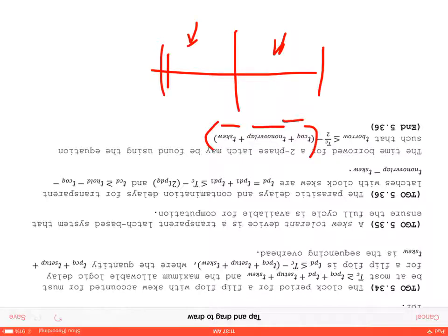So we were able to borrow this amount, some sort of time here, because we had an amount that's greater than half calculated in the first latch or in the second latch, and then we're able to borrow that extra time. But in this case, we also have to account for skew because the skew's at the end after our setup time. So therefore, that cuts into the amount of time that can be borrowed.